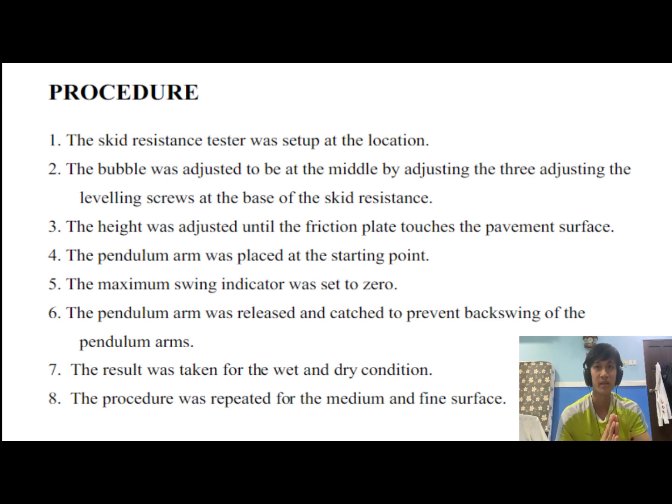By doing this, we have to set up the pendulum and let it swing freely, which means there is no contact with any surface, and when it swings freely, we immediately stop the pendulum from swinging back to get a precise 0 value. Once we get a precise 0 value, we start taking readings.